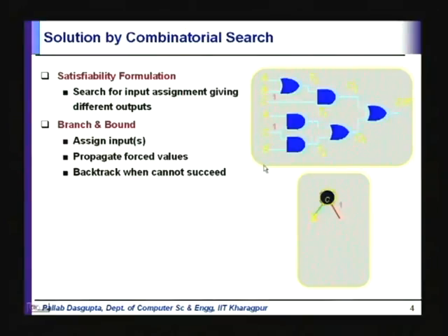So we set C equal to 1, but if we set C equal to 1, we cannot get the values of O2 and O1 right now. So we need to choose the values of the other variables. Suppose A is 1: if A and C are both 1, then we find that again the difference is 0. So we discard this path of the search, and say that when C is 1 and A is 1, there is no hope of finding a difference between the two circuits.